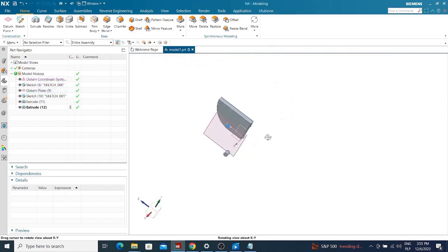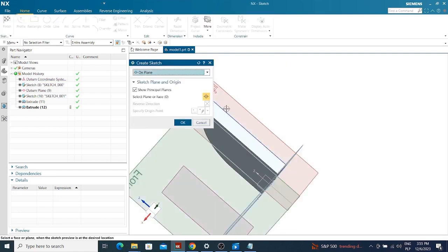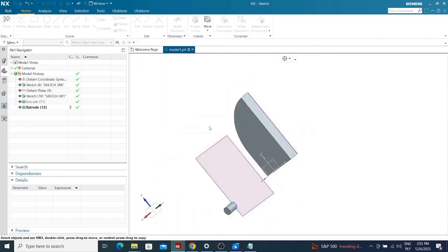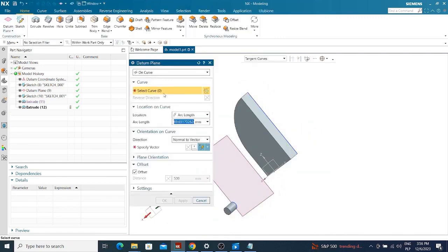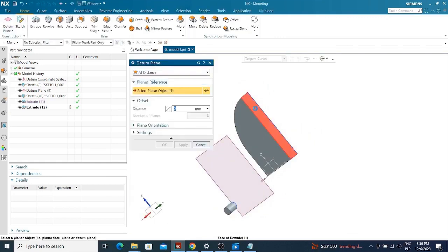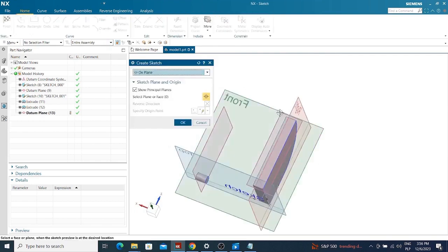Alright, the next plane I can create is, for example, a sketch that I can make, for example, on some face of a solid. I don't recommend this. It's better to simply choose an auxiliary plane. This way, we have more control over everything, and just add distance, even if it's 0, and then I open another sketch.